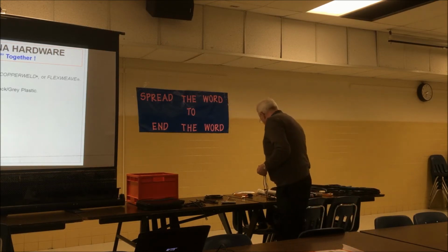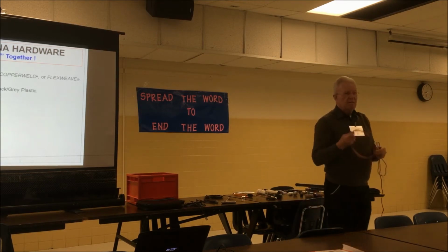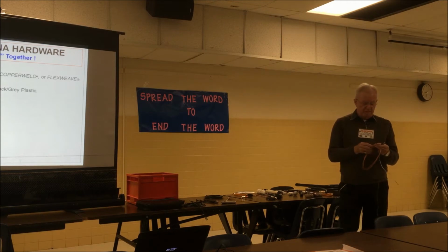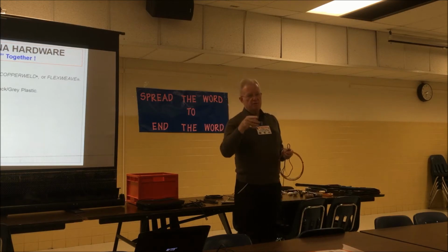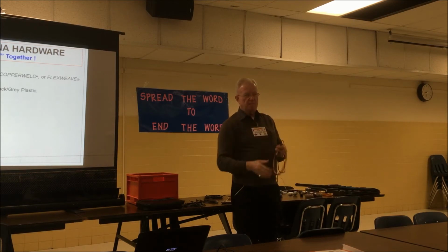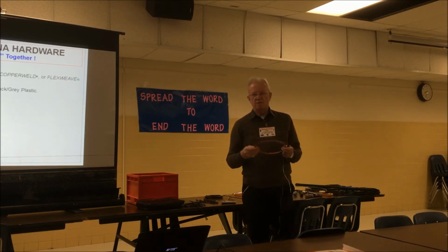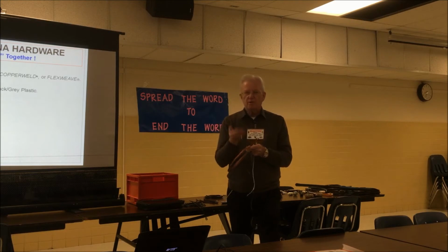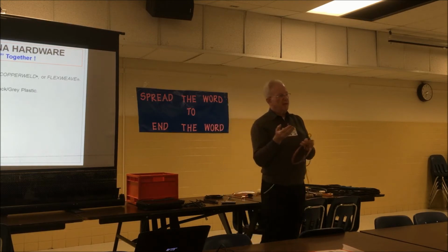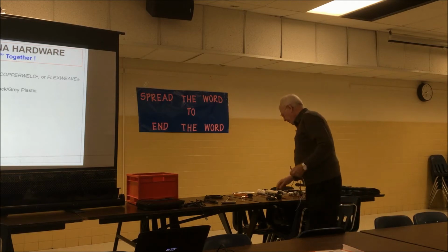Copper weld, I think I told you all what I think about this. This is copper-coated steel. It's very springy. Please, if you're using this, wear safety glasses. It'll come right back to you in your face. And I found that when I leave it out more than 3 or 4 seasons, the rust where you've dinged it will come through and you'll get a bad connection. So I quit using this completely.